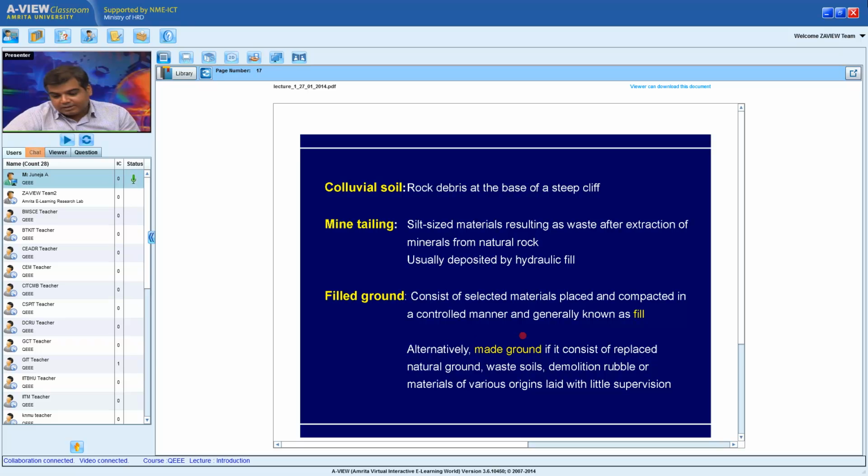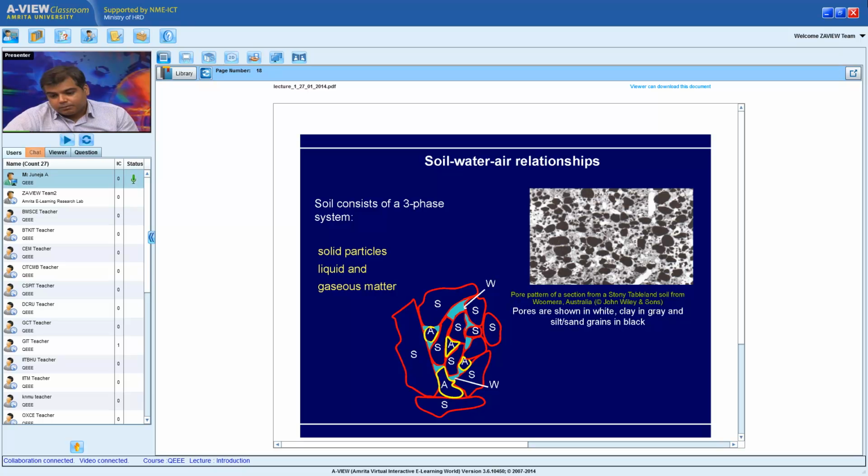This is a term which you'll normally find in many geotechnical investigation reports, wherein the near surface soil has a good amount of waste, meaning any rubbish material, whether it's tiles, brick bats, other construction rubble, or even parts of a bathroom sink. Anything which is non-engineered and simply dumped is your made ground.